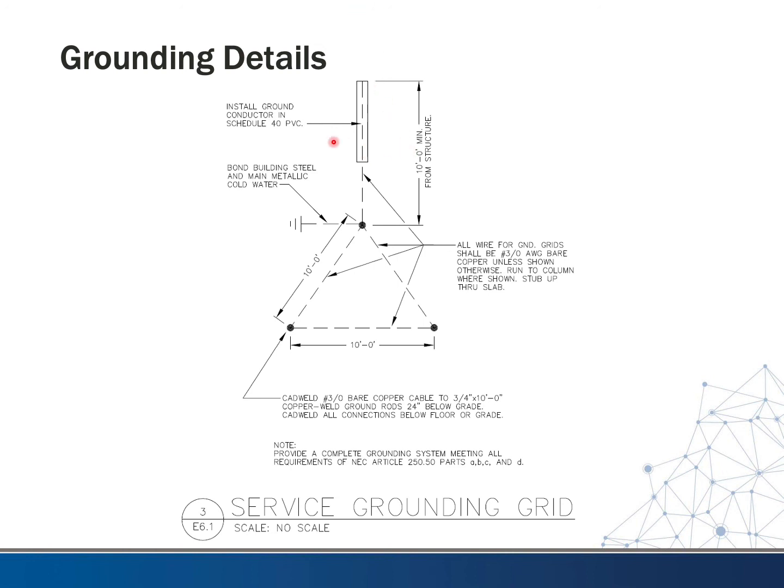And we typically use PVC conduit, a non-metallic rigid conduit, which I think we talked about when we talked about that conduit. If you use metallic, especially if the lightning protection system, if there is a strike or a large dissipation of energy into our system, this can produce an inductor effect. And so, as you know, with an inductor, you can't change the value of the current instantaneously. It has to be gradually. We wouldn't want that in our grounding system, so therefore we use the PVC to help alleviate that, so that won't happen. So again, another typical grounding detail to show how we connect the ground rods.